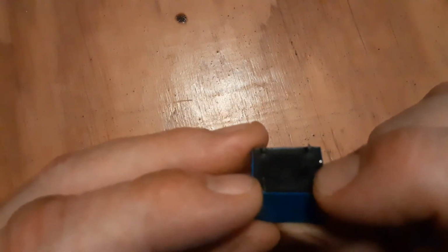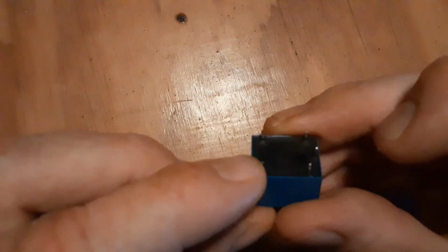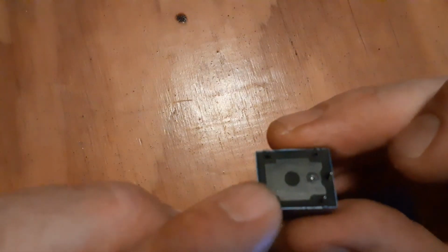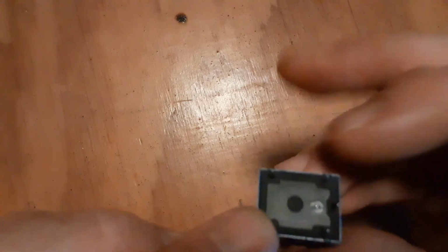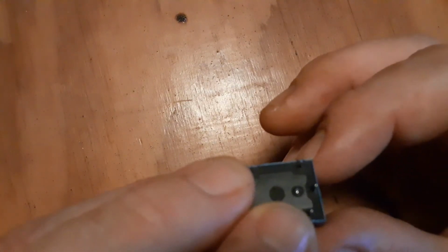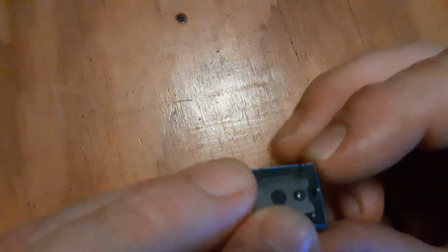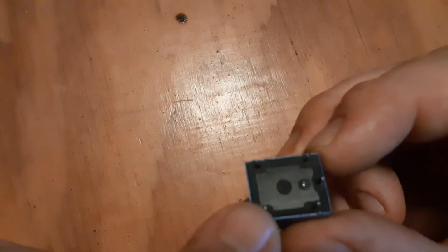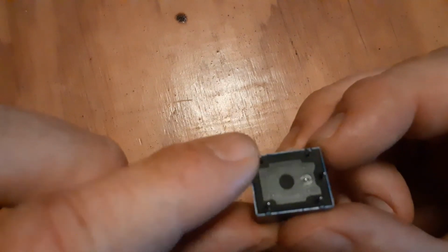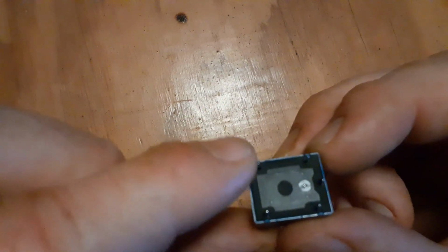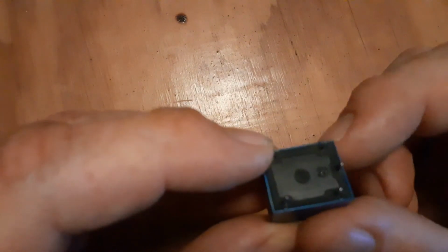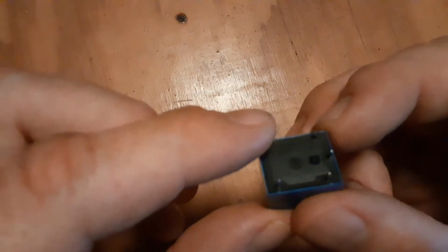And the difference is that this one is normally open. So normal means when the power's off. So if there's no current flowing through our coil, so our small current is off, then this pin is off. And this one over here is normally closed. So it's normally on, which means when there's no current, this pin is on.